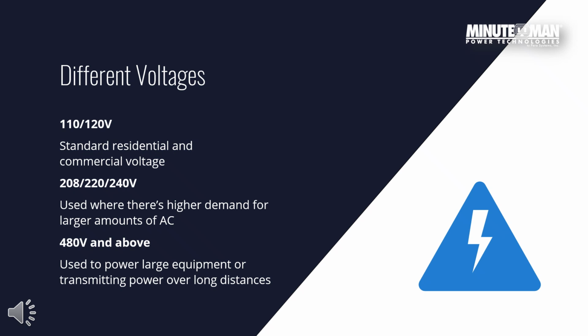How you identify voltage includes labels and nameplates on tools or equipment, color-coded wires, multimeter or voltage tester, and user manuals or product specs. Never assume, always verify.